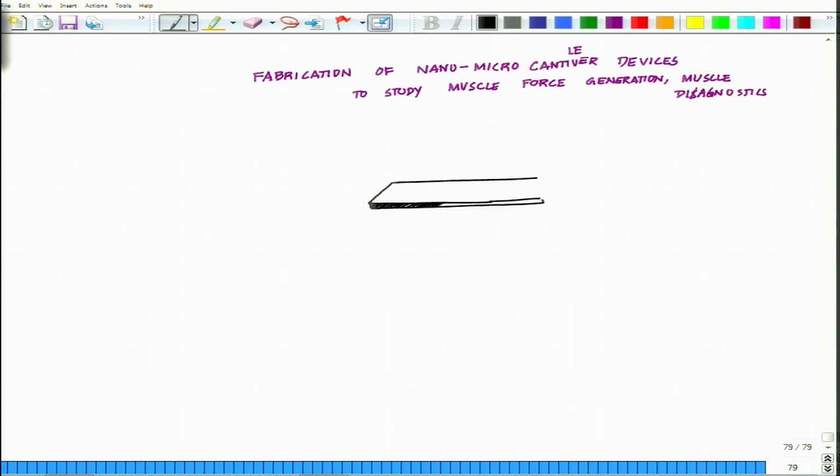This is how the plank is attached, and this plank can move like this as well as this. The person stands here or maybe slightly closer here, and the plank will be vibrating at a particular frequency, right? And of course, a person is jumping into water out here, and the plank is at a height. So, essentially this is a classic situation of a cantilever.